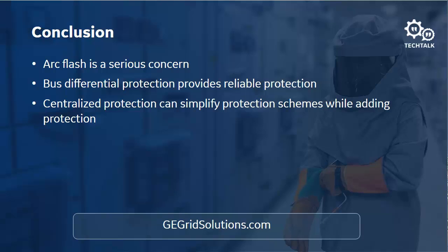So the question here says, in terms of arc flash protection, is zone selective interlocking or differential protection, bus protection, kind of outdated nowadays, as there are several technologies available based on light and overcurrent detection, which is more reliable and faster? So there are light sensors. I think there are issues with that just because of trying to place these sensors in appropriate positions to see the flash and to not damage the connector when you're placing these.